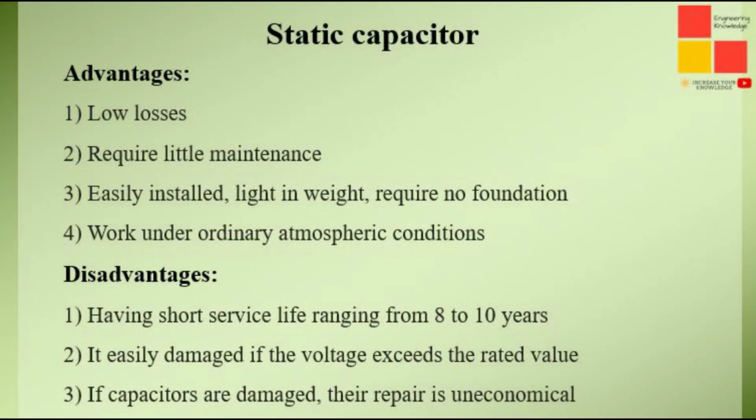The advantages of static capacitors are given as: low losses, require little maintenance, easily installed, light in weight, require no foundation, and work under ordinary atmospheric conditions. The disadvantages of static capacitors are given as: short service life ranging from 8 to 10 years. They are easily damaged if the voltage exceeds the rated value. If capacitors are damaged, their repair is uneconomical.